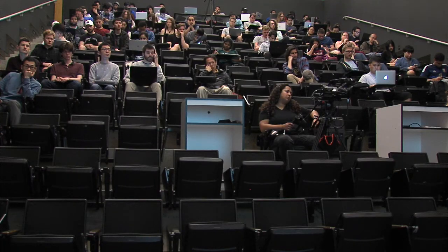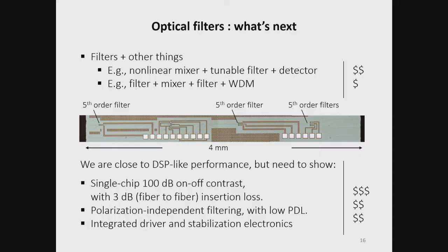Once we add in the fiber insertion losses, definitely there's a hit. Very good fiber couplers tend to have about 1 dB insertion loss, but that's the whole project in itself, making very good fiber couplers. Making very good fiber couplers together with this kind of stuff, that's still an open challenge. So typically we'd see 6, 7, 8 dB end-to-end insertion loss, and that's frankly not that great.